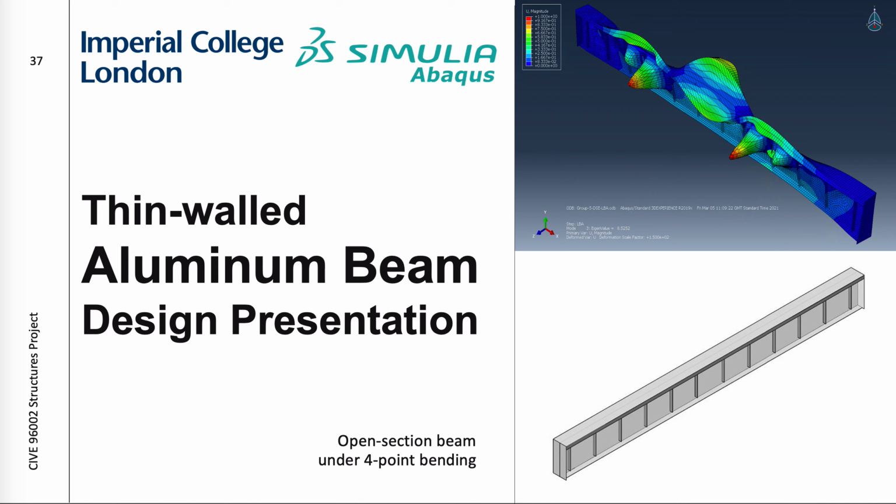The end result was a beam that is fairly optimized with some contingency for safety. This meant that only very small, minor improvements to the beam were possible, such as removing a couple of web stiffeners and reducing the size of end plates.